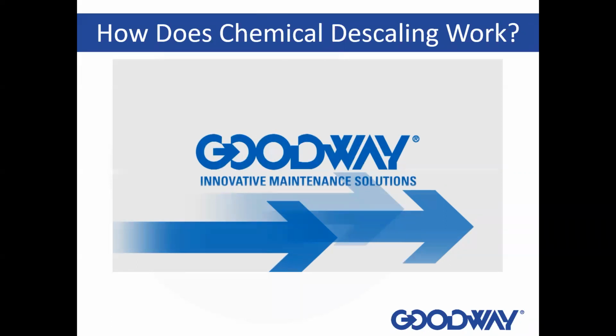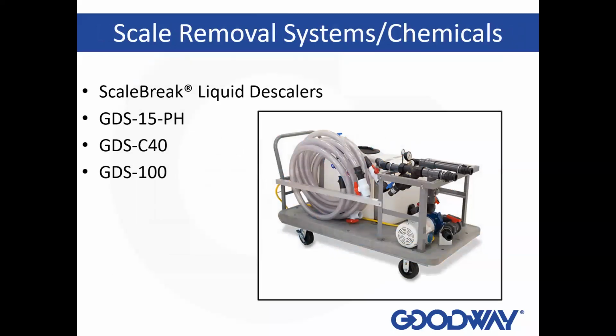And we talked a little bit about the importance of movement while this is happening too. So if you're looking to descale a boiler, you need to have water flowing constantly. It doesn't have to be at a high pressure, but you have to have enough flow so that it's moving. Why is it important for the descaling acid to continue moving when you're cleaning a boiler or heat exchanger?